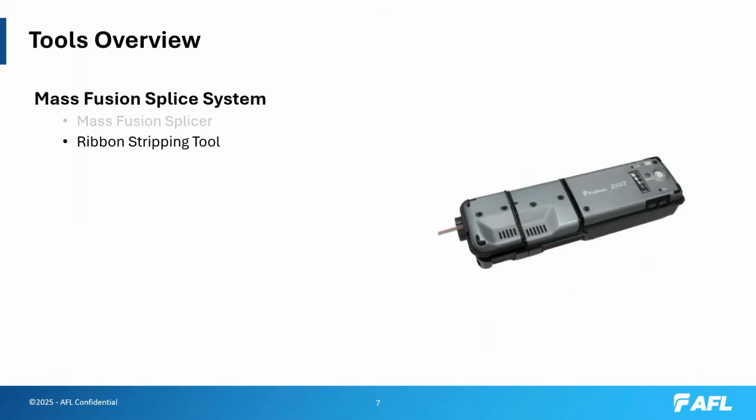Ribbon stripping tool. This is the mechanism you would use to remove the UV acrylic off the ribbon array. And when I say ribbon array, that can be what we call encapsulated ribbon, or rollable ribbon, or individual fibers that have been ribbonized into a ribbon array. The hot jacket stripper will apply heat to the section that needs to be removed. It helps loosen that primary jacket, which is the UV acrylic, off the cladding of the fiber, and helps you remove that material as easily as possible. Without heat, you would experience a lot of fiber breaks and have a real difficult time getting through this step.